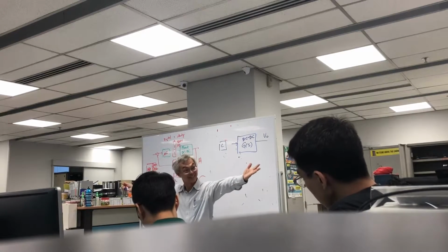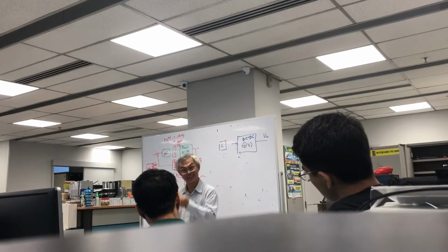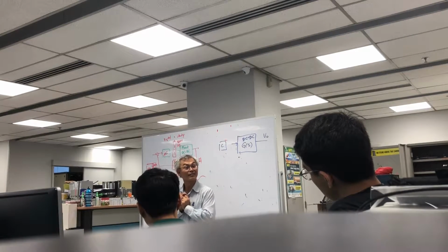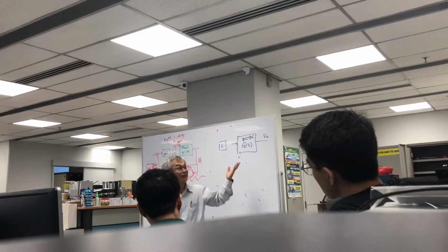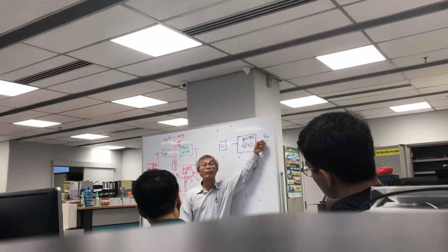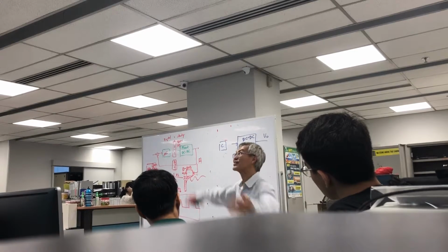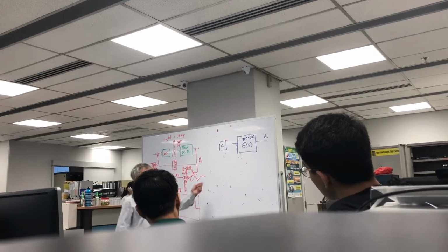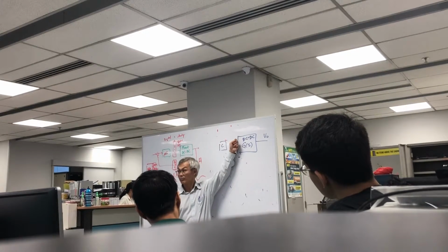I'm now in this class. I want to change your learning behavior. I need to ask, what do I have to do in order to change your learning behavior? I said tutorial question, right? Alright, so your DC-DC converter, what do you have to do to change the output? Function generator? You see, that's where everything goes wrong. You change the duty cycle of the PWM signal, alright? Agree?